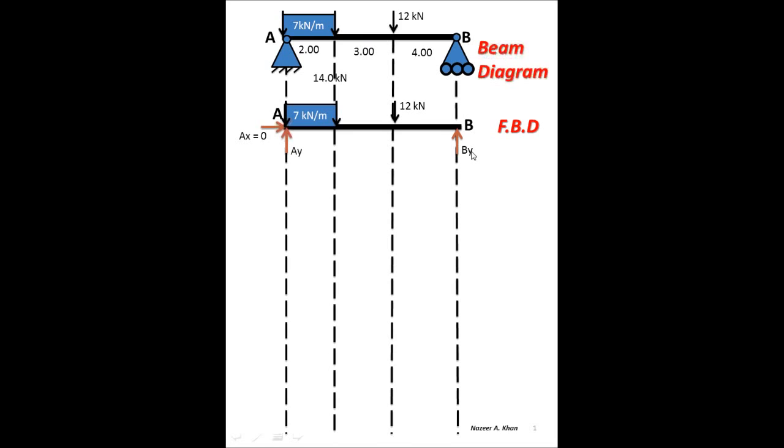With the requirements of an FBD, you're drawing it with a straight edge. You have to have all of the loading involved. If you don't have magnitudes, you're going to label them. You're going to have dimensions. Well, I'm not going to repeat the dimensions because they're right up here, and that's one of the reasons for stacking the diagrams too. You don't have to repeat certain types of information. They're right there. Okay, so I have my dimensions in here.